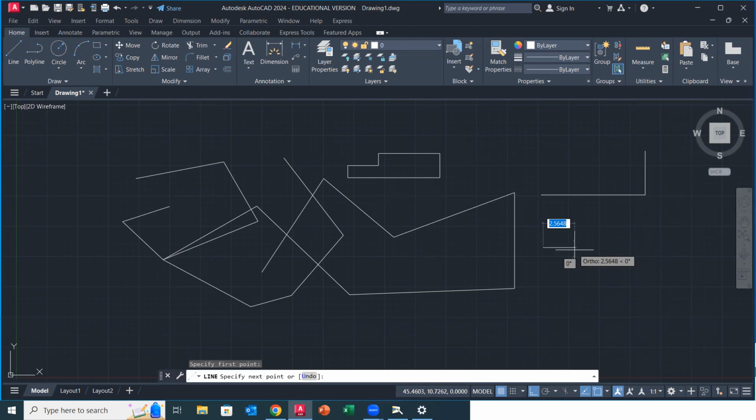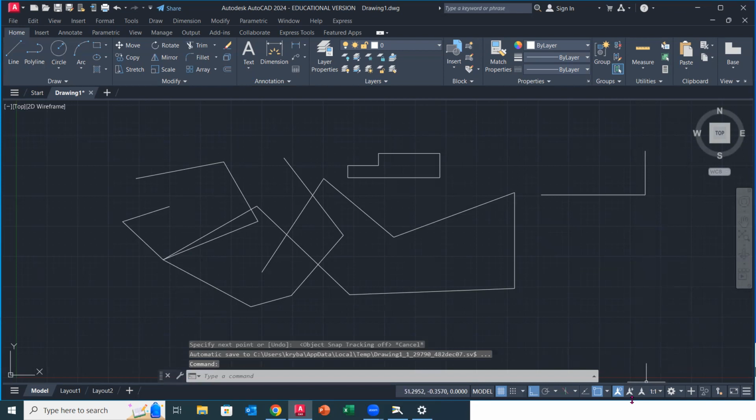be over here. We're not going to get too deep into it, but what that does is you can set up your angles so that you increment for any angle at 1 degree, 5 degrees. I can tell that this is set at 0 and 90 because it's only letting me go between those two. So that's going to be the default that AutoCAD is right now. But we can set that to 5-degree increments for angles or 10 degrees or whatever we want that to be. So I'm just going to turn that back off and hit escape.